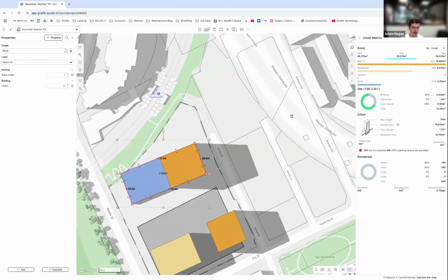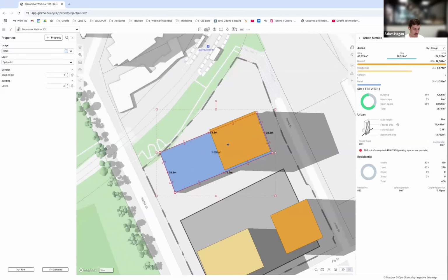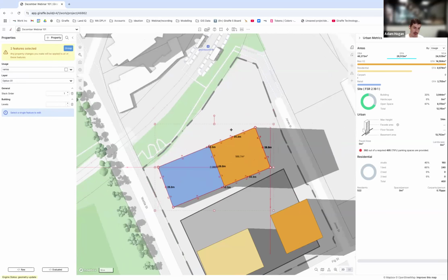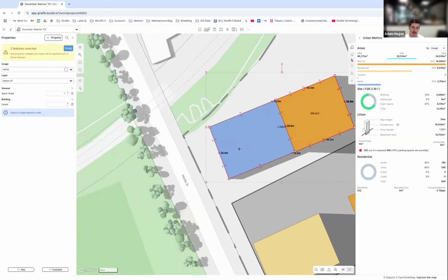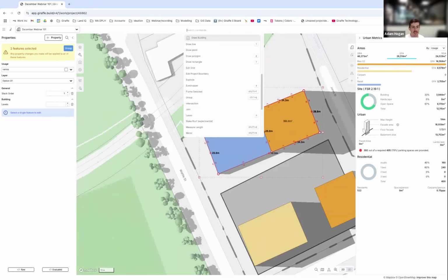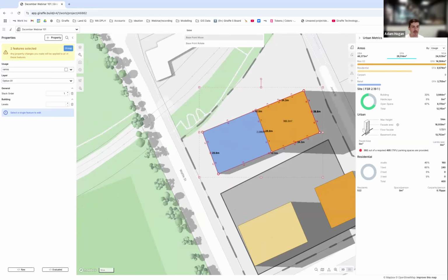So if I toggle into 2D mode, and we'll undo that and make sure we grab both of them, I can drag, and you will notice that I'm very askew from that front boundary. So in order to align that, if I hit spacebar on my keyboard, again bringing up that command list, I want to use a base point move.